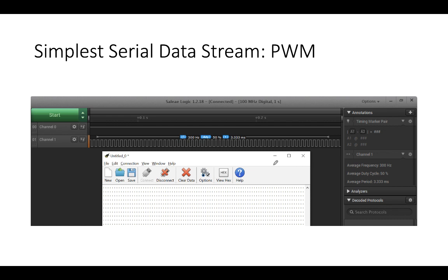All right, so those sequences can be pretty complicated, but we can also send really simple transmissions as well. They're not really full of meaning, but at least we can show that there's a transmission going on between your microcontroller and your computer. And sometimes when you're getting started, that's really where it's at. If you want to, you can send data from your microcontroller to a computer over 1 or 2 pins using GPIO or using a timer. And you can send really, really simple messages just to make sure that you've got a connection between the two. And when you're developing, that's often a really good idea.